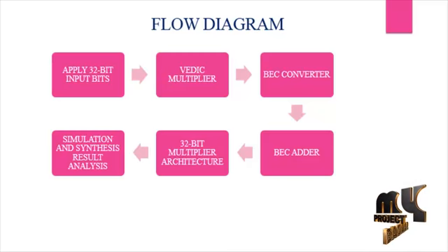Generally, the speed of the processor determines its performance. High speed processing is an essential requirement for all systems. Multiplication is a significant operation in digital signal processing and the arithmetic logic unit, and thus the demand for high speed multiplication is continuously increasing in modern VLSI design. Our research focus is on high speed multiplication using Vedic mathematics. Earlier, multipliers like the Booth multiplier, modified Booth multiplier and array multiplier were considered for high speed multiplication, but these involve a large number of intermediate steps which reduce their speed as the number of bits increases.